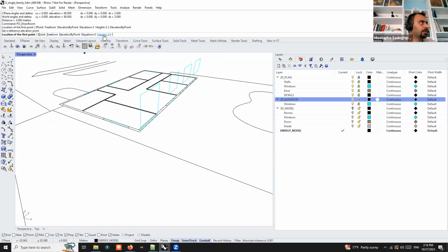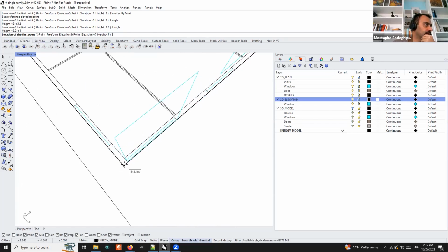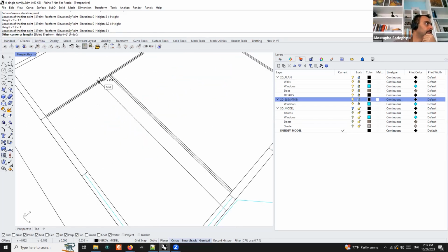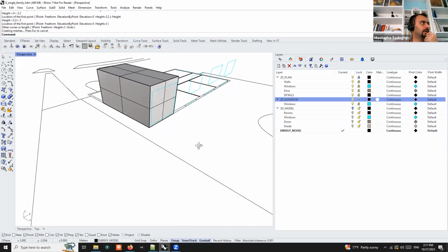The other one is the height of the room. So I just measured and I know the height is 3 meters. So for you, if it's different, you can click on this and type the value, right? I can change it to 3.2, for example. But click here, type 3, and that works. So now that I have that, by default, PO draw room draws rooms as rectangles. So I can click here from one corner, go all the way to the other corner, and the room is drawn.